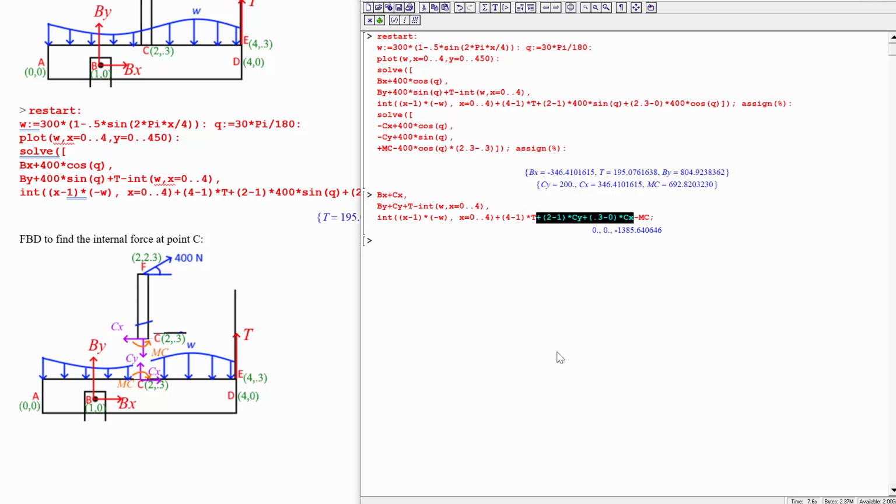Aha. Looking through the way we added these all, one of the torque components is wrong. Can you see which one? So this one here, the Cx, actually we're at a displacement of 2 up. This creates a torque in the negative direction, so we should have subtracted that instead of adding it. Now it's worse. Aha! The problem is that we made that same mistake in the first one. When we were calculating the contribution that the x component had to this force, we should have subtracted that as well.